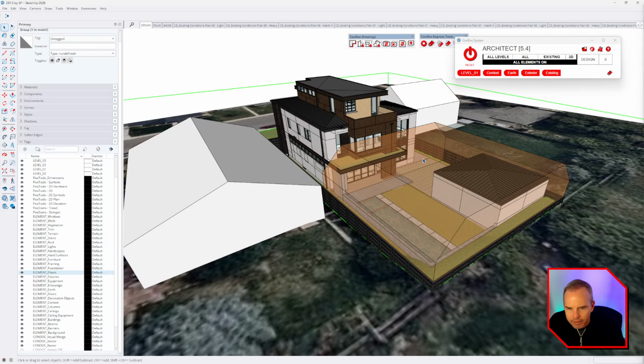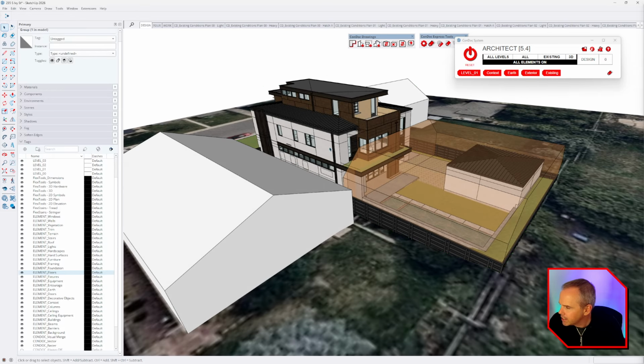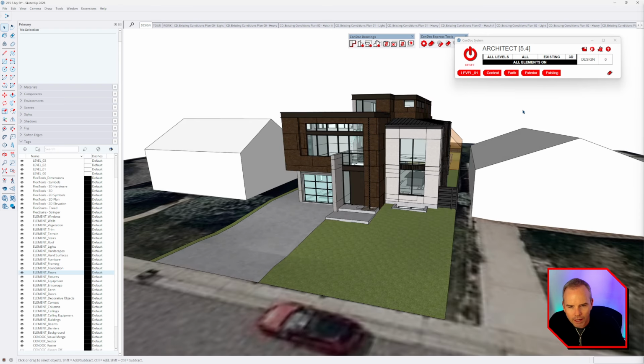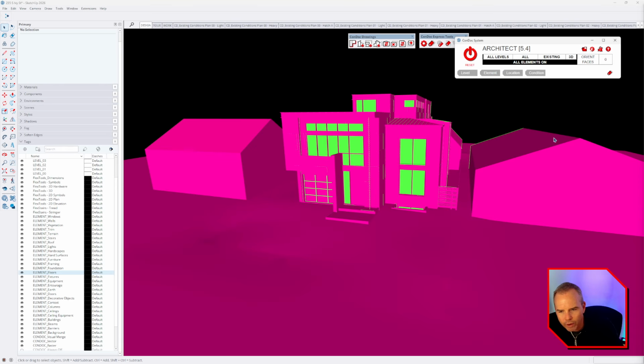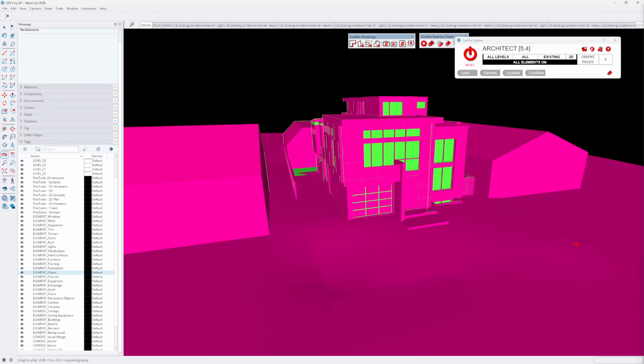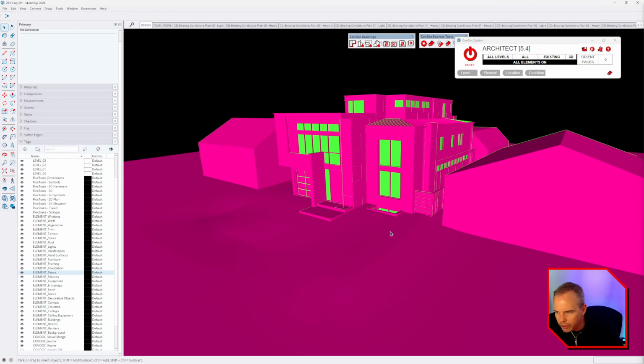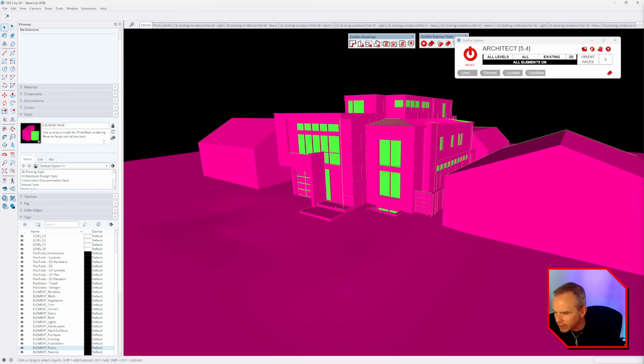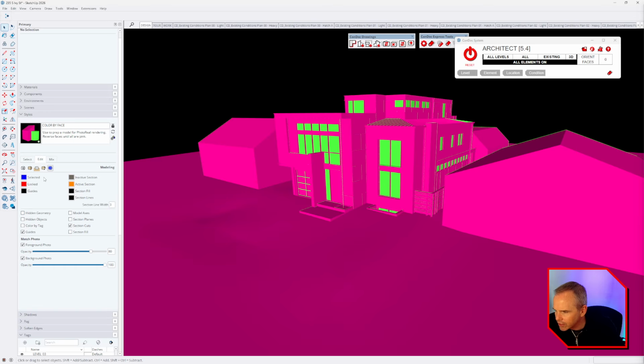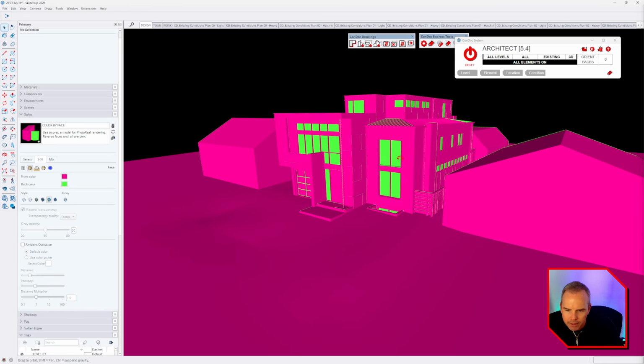Okay, then one of the last pieces here, second to last, is going to be our utility styles, and this came from my book. So orient faces, this is definitely of value. Orient faces will show you, all this is doing is setting a color by face, whether it's the front or the back. And if I look at what this style is doing, you can see that the front is pink and the back is green. That's all.